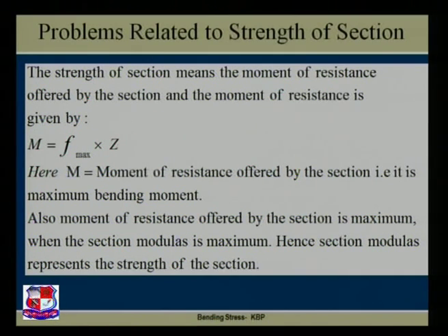Also, the moment of resistance offered by the section is maximum when the section modulus is maximum. Hence, section modulus represents the strength of section.